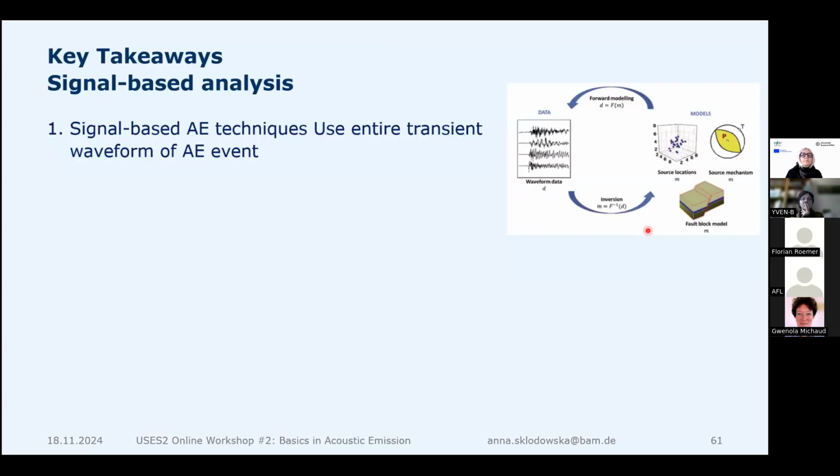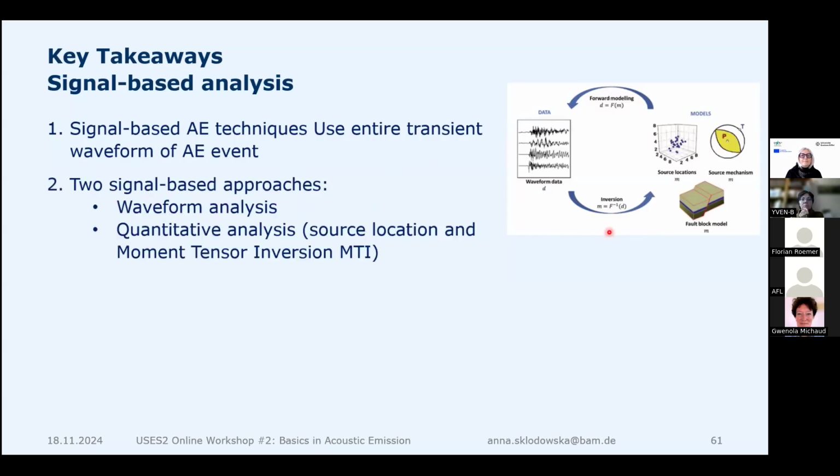Okay, to sum up this part, I know it might be a little bit chaotic in here, but we have signal-based acoustic emission techniques, which use the entire transient waveform of the acoustic emission event. We have two main types of approaches: waveform analysis, and quantitative analysis, source location and moment tensor inversion.